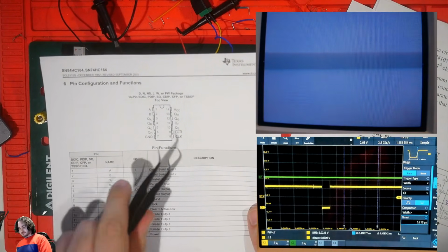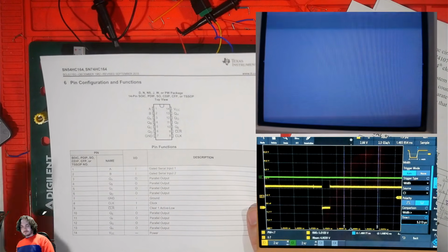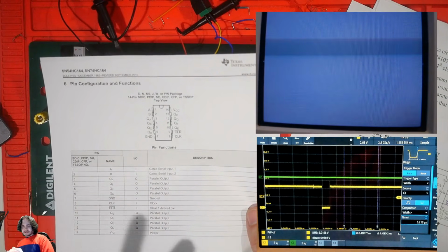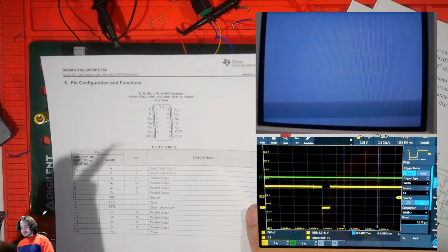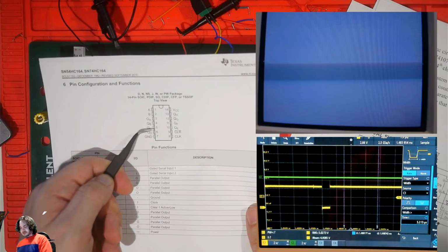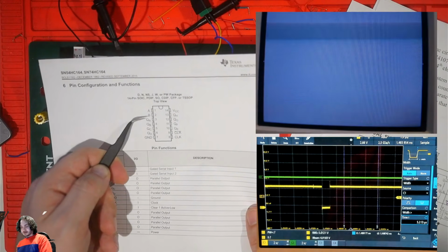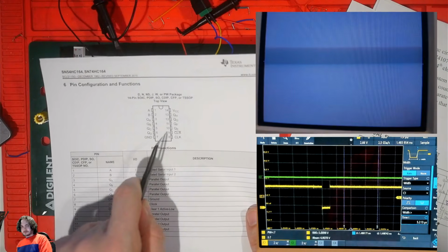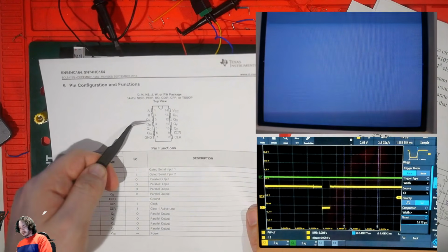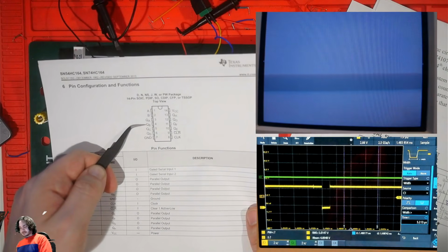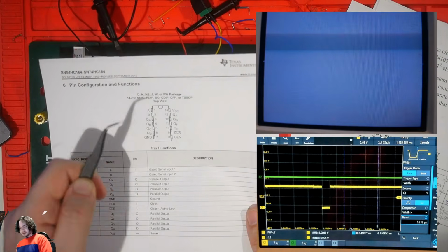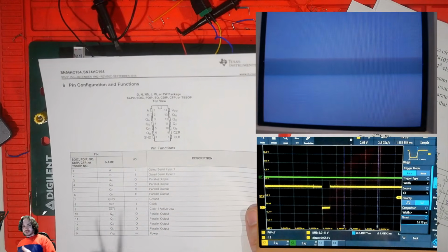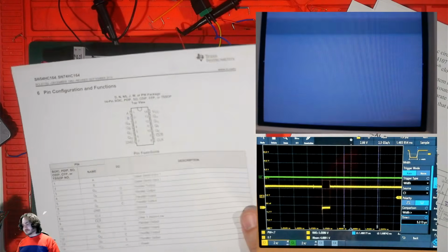If we were to put into A and B that 3.5 megahertz signal, we're sampling it, and then clock is 8 times higher frequency, what's going to happen is that each of these is going to be outputting that square wave, but offset by 1/8 of the time of a full cycle. And this is going to create one where B is a little bit delayed of A, and C is a little bit delayed of B, and this cycles around to being at QH essentially the same original signal, that 360 degrees.